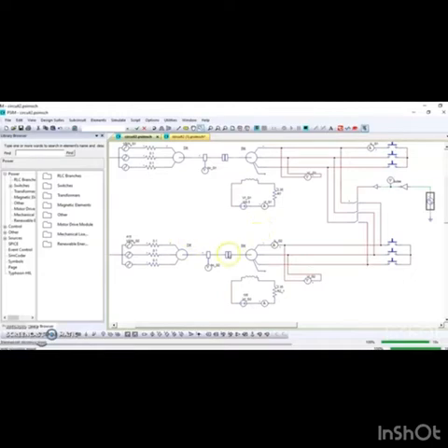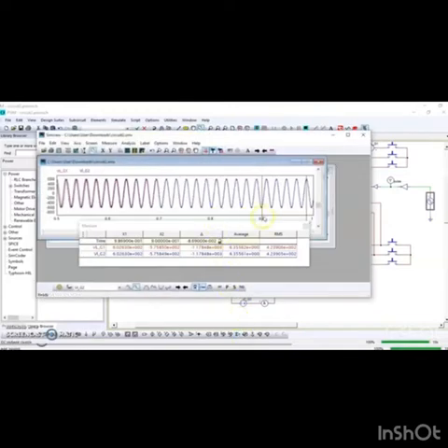From this circuit, we can conclude that when the time taken is 0.9 to near 1 second, both generators are not in parallel connection since the waveform is not in phase. When the time taken is 0.7 second, both generators are operating in parallel. Generator G1 and generator G2 are the same. The RMS value for both generators are the same, which is 433.9.